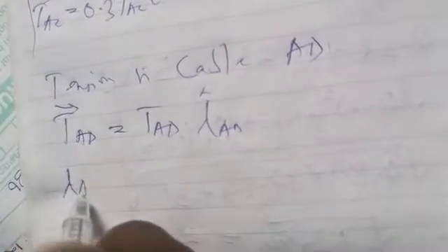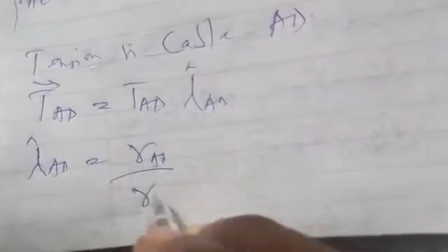We've done AB and AC, now cable AD, T_AD. The tension vector is simply the magnitude of the tension in cable AD times the unit vector AD. The unit vector in AD is the position vector AD divided by its magnitude, so this is simply r_D minus r_A, all over the magnitude of r_AD. So let's obtain r_D minus r_A.